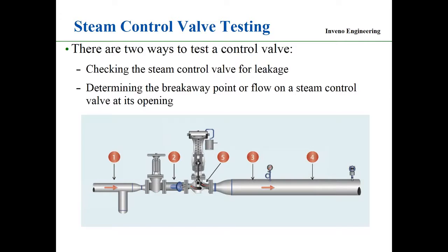Well, that's a common problem, but what we do is penetrate the insulation with a small hole we call a test plug. So you make an opening in the insulation so the probe can go in and make contact with the line. Once the test is done, then we plug that hole with a plug we call a test port plug.